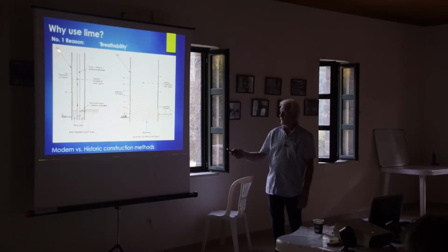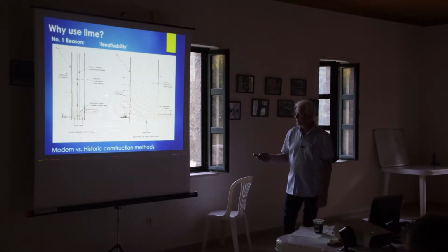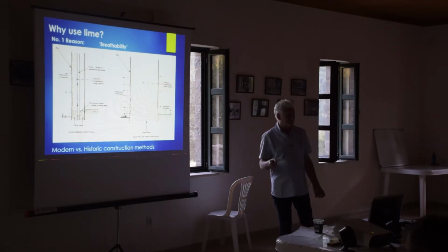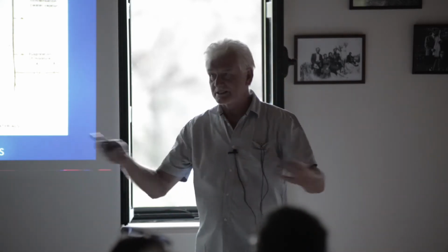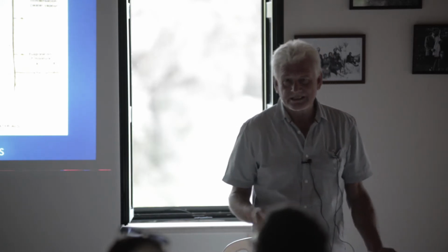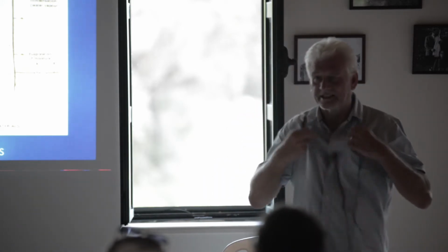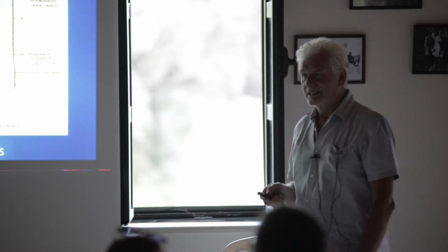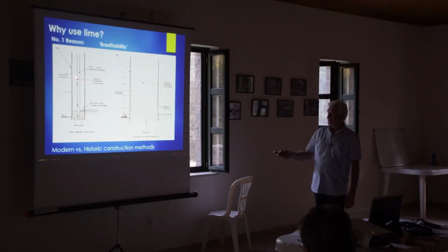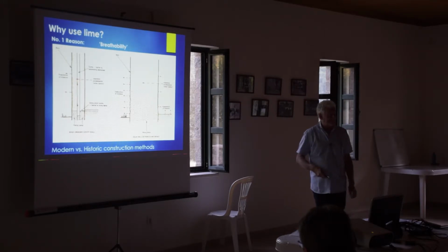So the rain will run down the building. Within the structure, you have what's called interstitial condensation, and there is in this building now. We have significantly added to it by our presence, because we're all hot and sweaty and the air is wet and humid, and the water is going into the walls. That water can travel through to the first wall, but not the second, and it comes down the cavity and out.